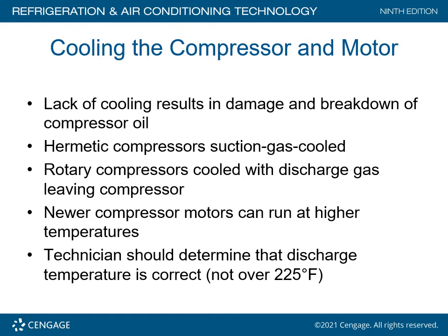Well, Larry, how do you measure that? It's very simple. You just take a thermometer or a sensor and attach it to the discharge line. We do not want to see that temperature above 225 degrees. If it's much higher, you need to find out why and take corrective action so that you don't destroy that compressor, because the oil is overheating at a temperature above 225 degrees Fahrenheit.